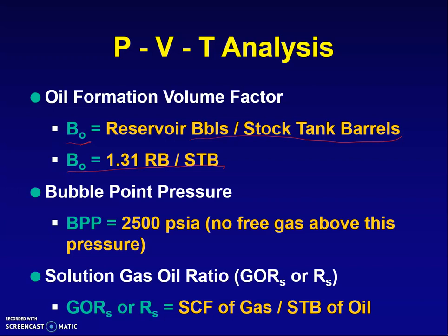Bubble point pressure is the pressure above which there is no free gas, as we discussed again in the PVT, pressure temperature diagram. And you see that the bubble point pressure changes with temperature, right? So this is called the bubble point line, and all those points on this curve up to the critical point are bubble point pressures at different temperatures, depending on what the reservoir temperature is.